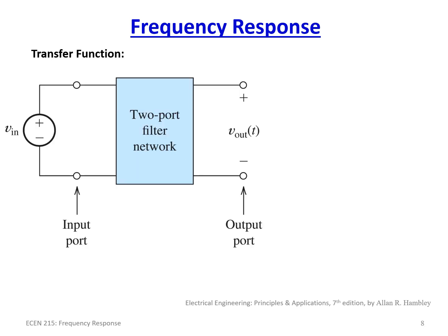So a transfer function is just a relationship between the output to the input based upon frequency. Because in the end, we've got this network here, and we just want to have some way of relating the output to the input. So the input amplitude and its frequencies are an unknown, but this is a known network. We can actually compute the components of this network, the impedances, and come up with what's known as a transfer function relating output to input.